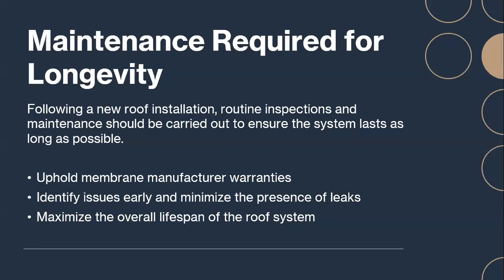Following a new roof installation, it is important to get a plan in place for routine inspections and maintenance for a variety of reasons. Not only is it going to expand the overall life of your roof system, especially upfront, it's going to be helpful in regards to manufacturer warranties. Most, not all, but most of the membrane manufacturers have stipulations within their warranties that maintenance does need to be completed in order for the warranty to be upheld. It's also the best way to identify issues early and deal with any small damage before it becomes major, and provides the biggest potential to identify leak issues before they happen.